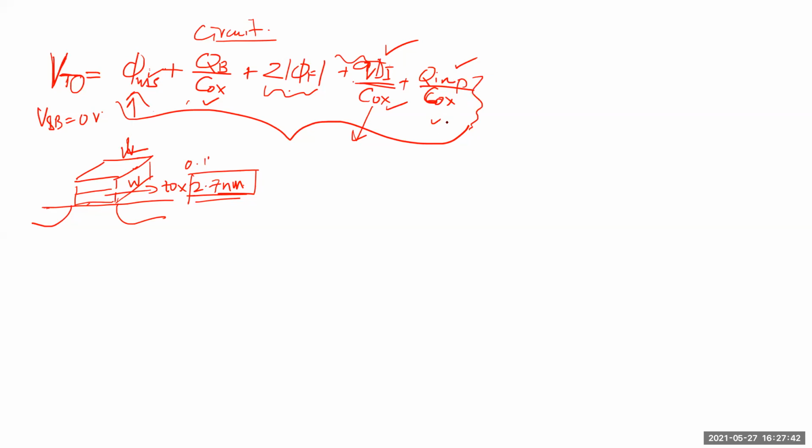So I think a lot of people are saying I can change the oxide thickness and all that. No, you can't change those. As a designer, you can't change it. That is something which is given to you. Once you choose a process, you say, I want to go with the 180 nanometer TSMC process, these are what's given to you. Now, there are different flavors of devices. They'll give you a high VT, a low VT, an IO device and all that. But for those given devices, it's fixed. I can't do anything about it. Okay, is that clear to everyone?